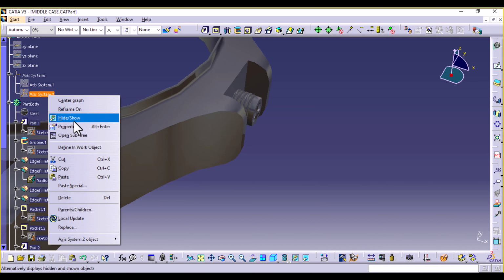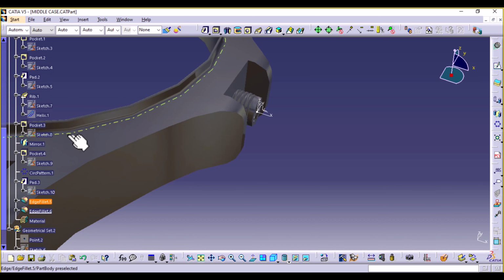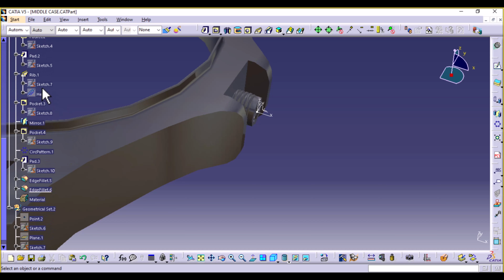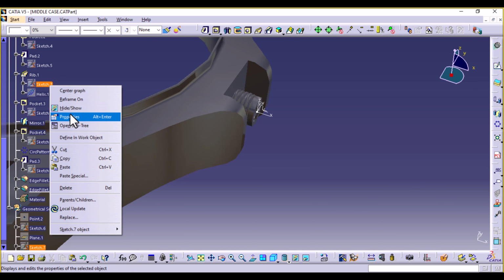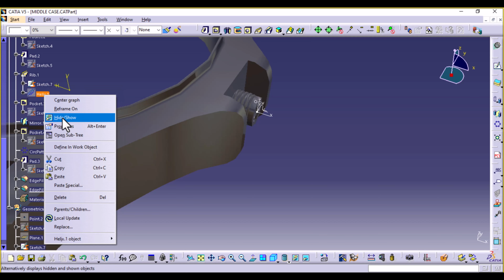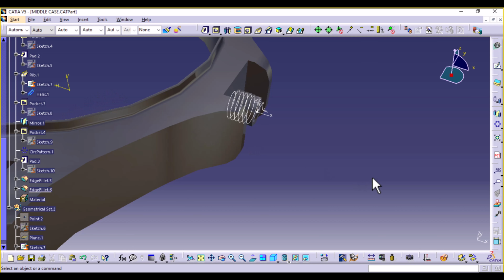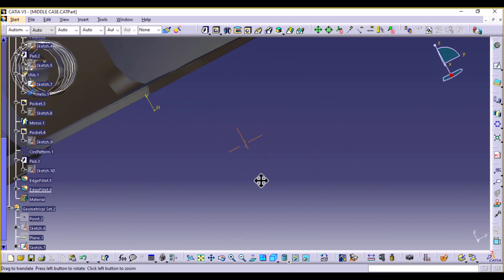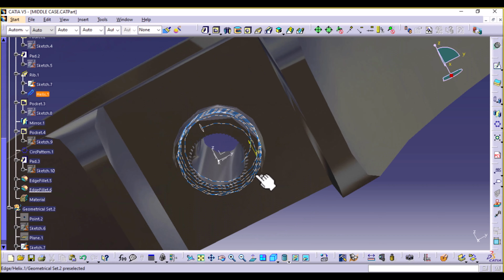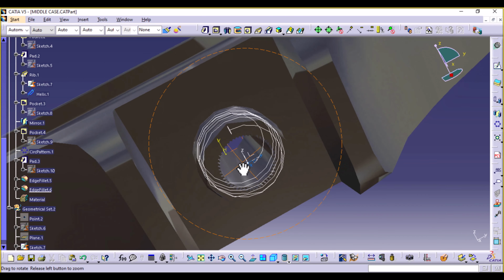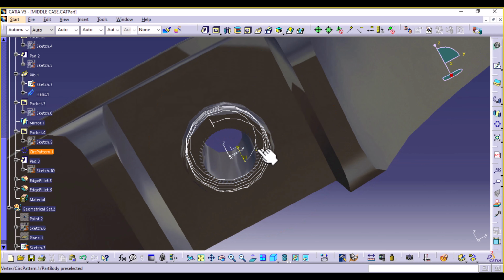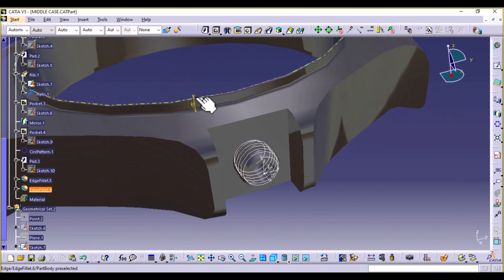So we had this axis system here. And if you look at the rib, it's being controlled by this sketch and this helix. So we're going to select those three elements. Oh, sorry, there's also another profile we created in here. There's a small pocket that we created here. But we can just ignore the pocket. So let's select these three: